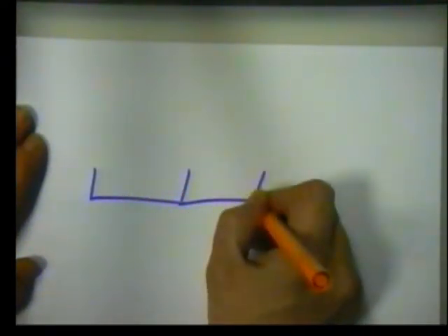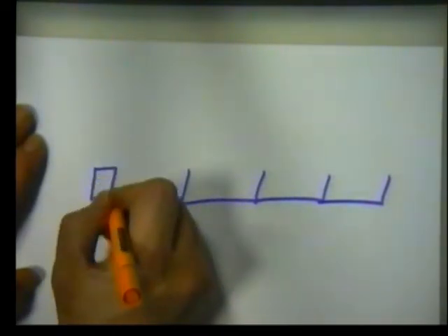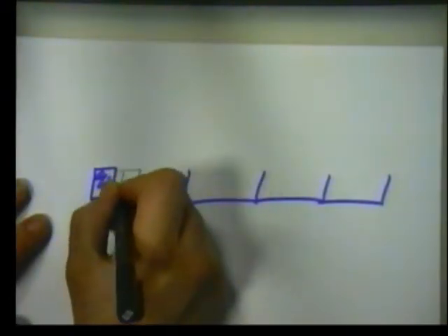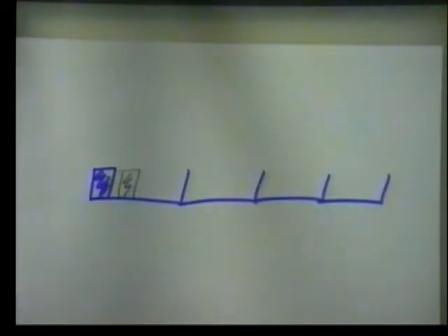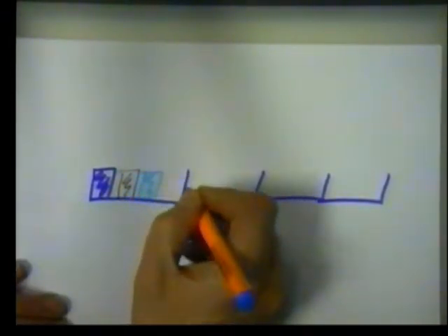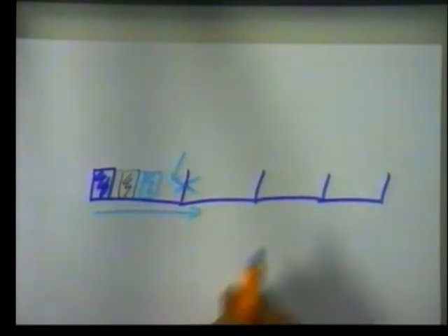What this means is that you have to look at what is the fastest interrupt. If this is the rate of arrival of our fastest interrupt, then all of our interrupt routines, regardless of how long they take, must be executable within that time frame. Because if that wasn't the case, you would displace the next time of arrival of the fastest interrupt.